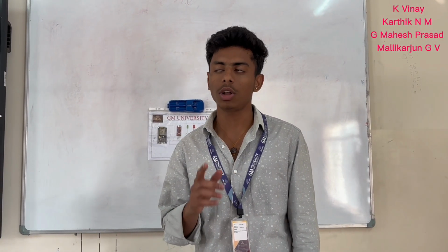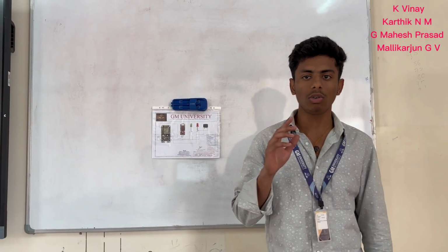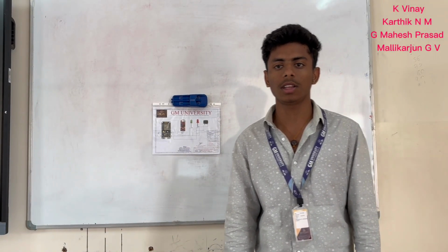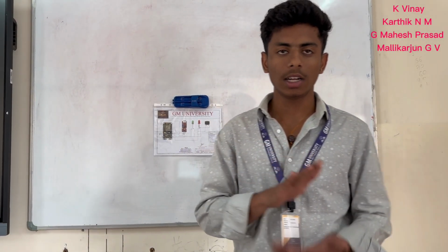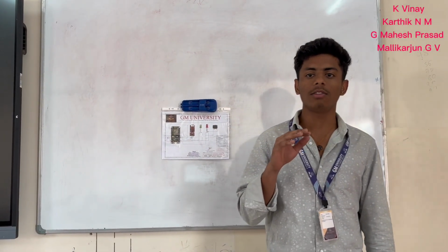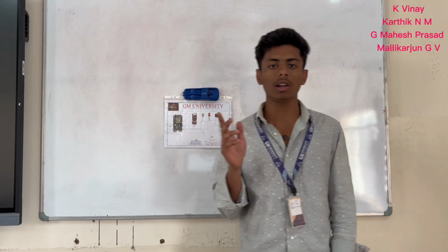The IoT noise monitoring system is designed to measure and monitor noise levels in an industrial environment in real time. It uses a sound sensor to detect the sound and a microcontroller, ESP8266 or ESP32, to process the data and send the noise data to the cloud through Wi-Fi, where it can be viewed on a web or mobile dashboard.